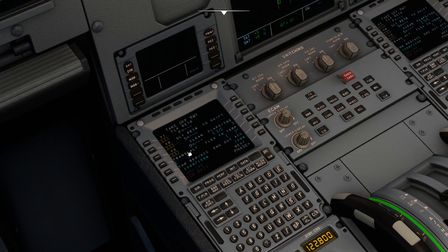And let's go to the performance, and let's quickly enter the takeoff performance. V1, rotate, V2 speeds. We plan our departure from runway 27 left. 27 left is 153, 153, 154. So let's get it entered to the system. 153, 154, again 154.